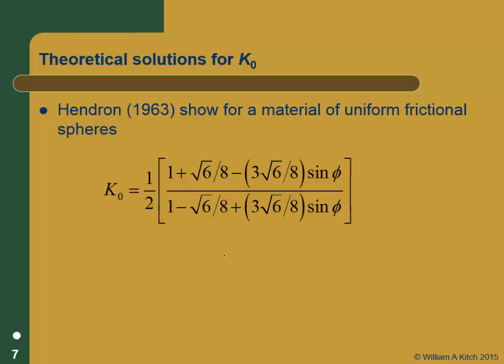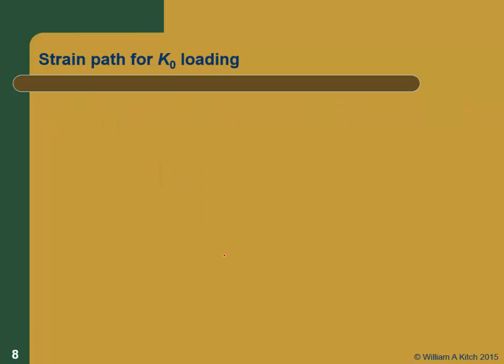So if you had elastic uniform spheres, and I don't know whether he used cubic close packing, he used a very, very uniform geometric spacing of them. So it's at least a decent first order model of soils. He showed you have this really nice relationship between the horizontal stress and the vertical stress if there's no lateral strain. That's nice.